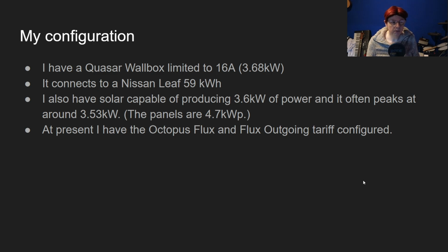Often, I've seen it generate up to 3.53 kilowatts. The panels connected to it go a fair bit higher than that, but of course the sun is very rarely in the right place that all of that energy can be captured, and this is the normal situation. You have an inverter for your solar system that is not capable of using all of the energy that it's provided with.